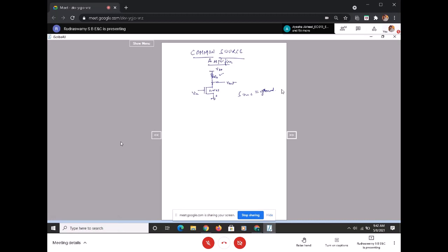So typically the static resistance or the resistor, the passive device that we are connecting as a load resistance at the drain terminal, occupies more area, and it dissipates more heat. In order to overcome this, we try to use something called the diode connected MOSFET. So instead of this load resistance, we'll try to use a MOSFET which will be acting as a resistance. We'll see what exactly this means.